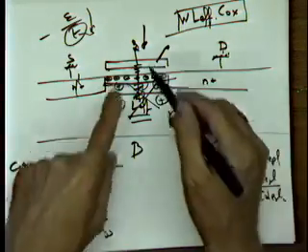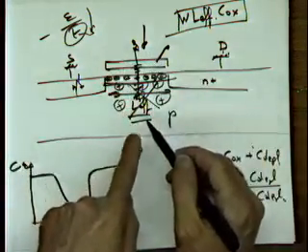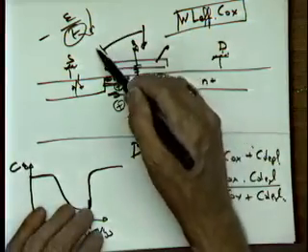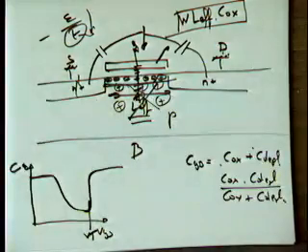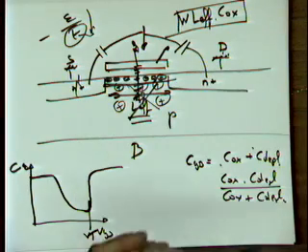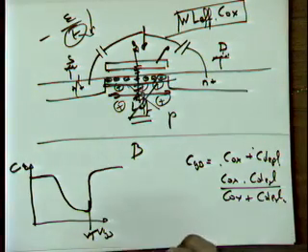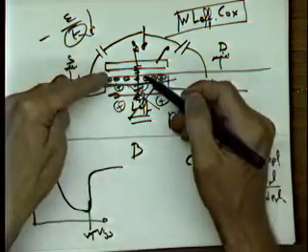But now the difference is that this capacitor is not going to go to bulk anymore, but it's going to be equally divided between the drain and the source, because you have this conductor sitting underneath the channel that connects the other plate of the capacitor to both the source and the drain. It's equally divided between the two. Okay, so, yes? Why does it go back up to WL Cox? Well, that's the only thing I have left.